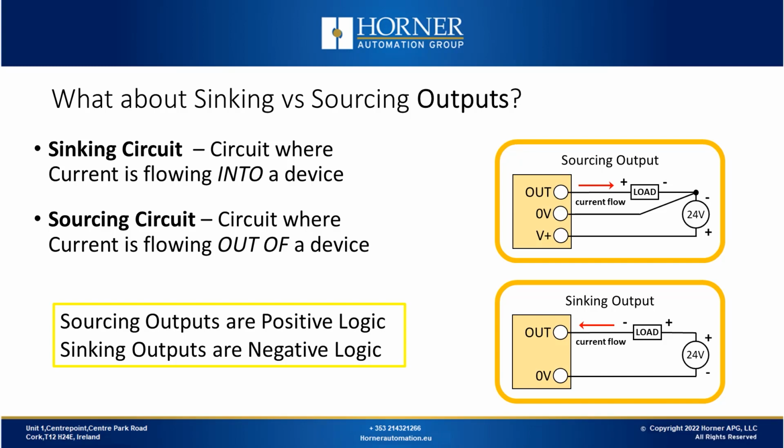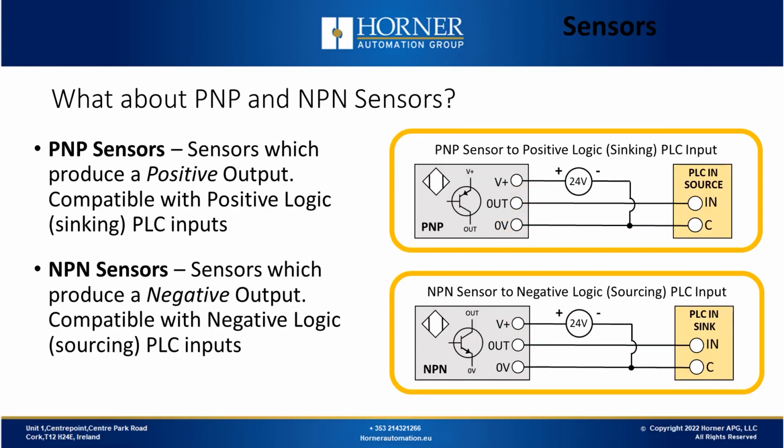So that's the relationship between syncing and sourcing, and positive logic and negative logic. Now we'll talk about PNP and NPN. These usually, from an automation standpoint, refer to sensor output. So it's what the output looks like on a sensor, whether it's PNP, NPN, or something else.